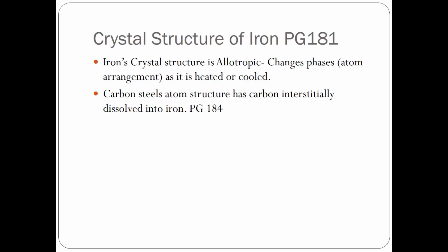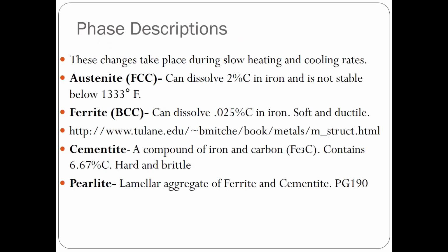Chapter 12, carbon steels, crystal structure. I would be able to list the common crystal structures that we talked about. Make sure that you understand the difference between crystal structure and microstructure. That's a huge problem on the tests. It was on the midterm for some of you, and it will be on the final for some of you, unfortunately. But make sure you know the difference between crystal structure and microstructure. Crystal structure is the atom arrangement, and microstructure is the phases.